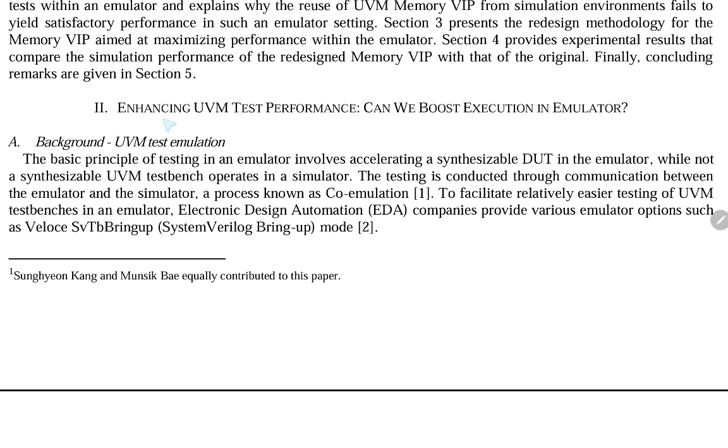Chapter 2: enhancing the UVM test bench performance. Can we boost the execution in the emulator? A. Background: UVM test emulation. The basic principle of testing in the emulator involves accelerating the DUT in the emulator, while the non-synthesizable UVM test bench operates in a simulator.